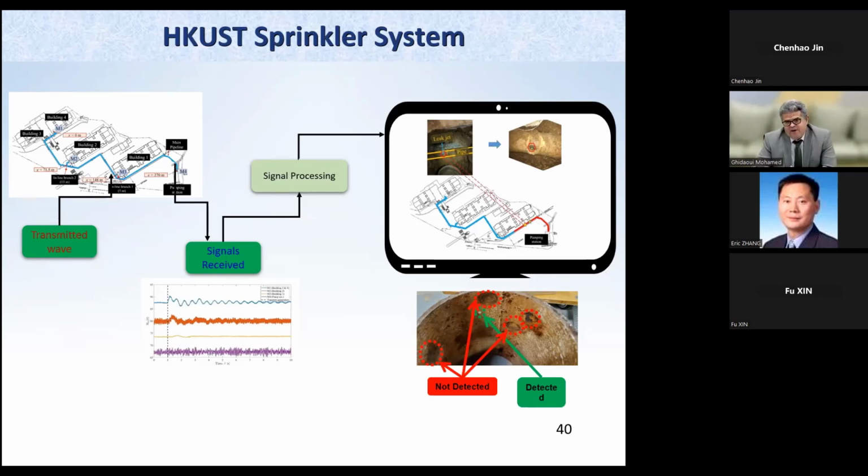So what we did, again, we found the leak using time reversal, and you see here there is this hole there, and that's where the leak is. And because of the pressure in Hong Kong, we drive our water using reservoirs and mountains, so the pressures tend to be very high, and therefore even a small hole will leak a lot. And the leak here, when everything was operational, is about 3 liters per second. That's a lot of water just from one leak. You can do the computation and you find it's tremendous, right? 3 liters per second.